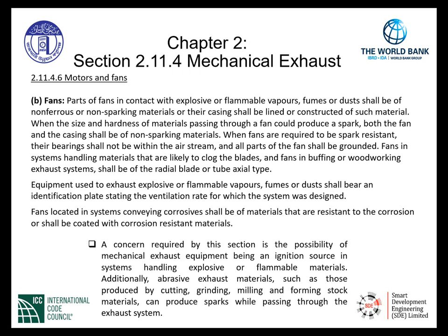Fans located in systems conveying corrosives shall be of materials that are resistant to the corrosion or be coated with a corrosion-resistant material or materials. A concern required by this section is the possibility of mechanical exhaust equipment being an ignition source in systems handling explosive or flammable materials.